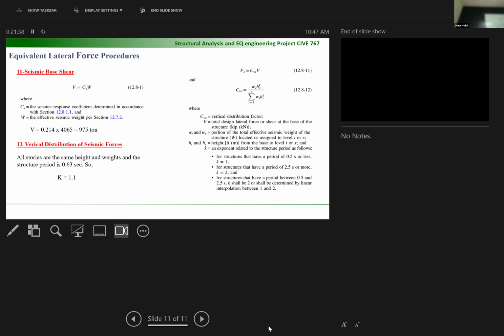But the thing is, we usually apply earthquake in the X direction and earthquake in the Y direction. Like, an earthquake is hitting in X, and there's another one hitting in the Y direction. So we say, all the earthquake in X and 0.5 Y, 1 Y and 0.5 Y. The geometry may be symmetrical, but then the building is not the same. Yeah, we can do that. Yeah, that's also one of the things.